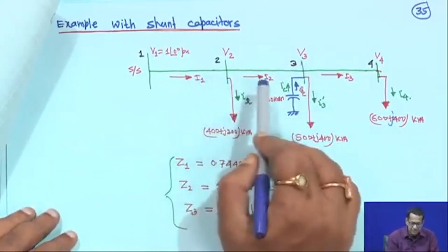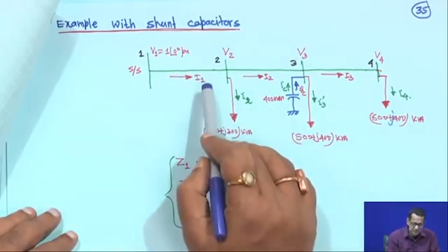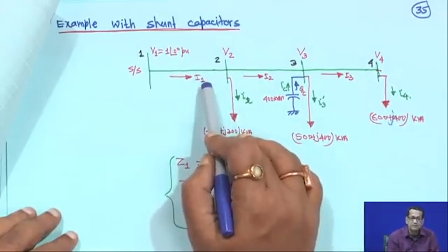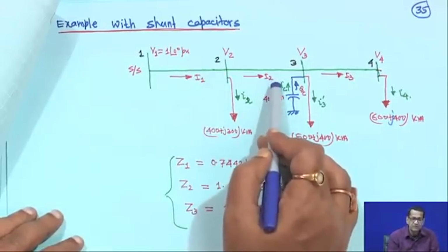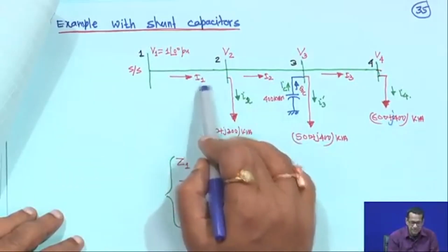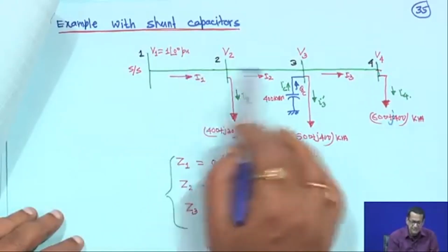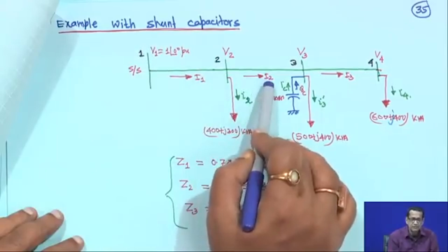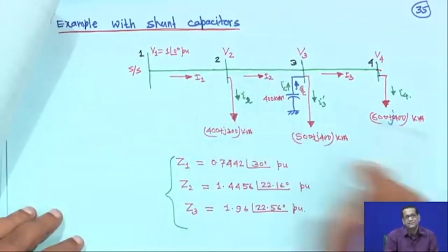Here also it will decrease, but this I1 is higher than this one for this example, that means the reactive component of this one is higher, and as soon as this IC comes, here also it will be subtracted from the reactive component of the current, but the reduction here will be much more compared to this one, because this reactive part is higher. So, loss reduction will be here, but if you take the same resistive values, the reduction will be more here and less there, if you assume the same R, right. But anyway it depends on the resistance as well as reactance of the branch, right.